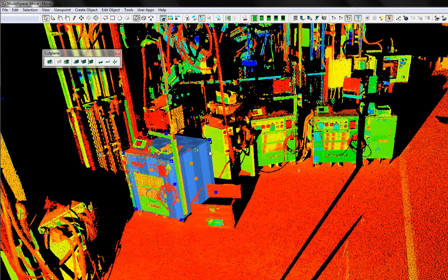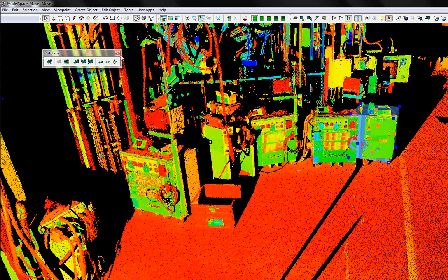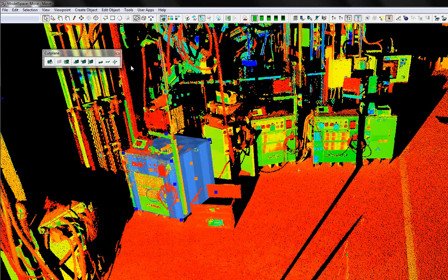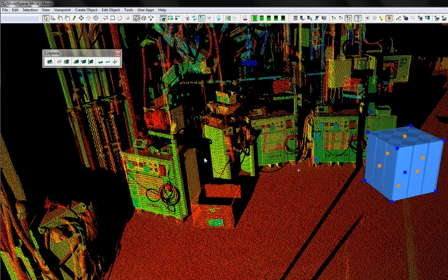Or if you don't even want to pick a source edge, you can just pick a location where you want it and say, I just want it right over there. You don't even have to do two picks. You just, boom, it moves over there. So when you're moving CAD objects precisely and quickly, the move by reference and move commands are really, really spectacular. And let's say you're a CAD operator that wants a little more resolution on what he's doing.